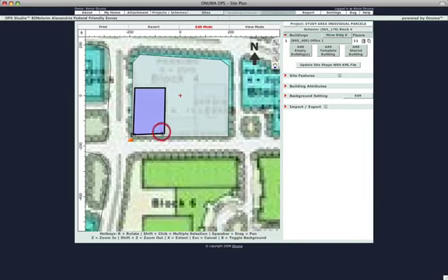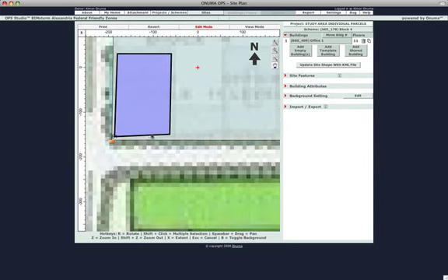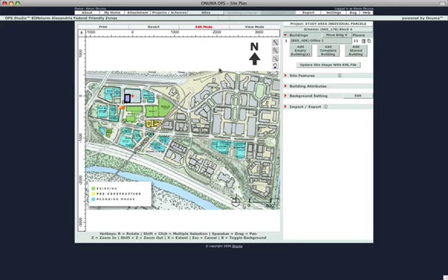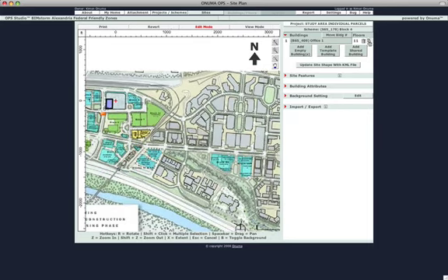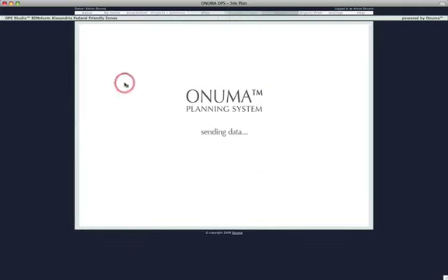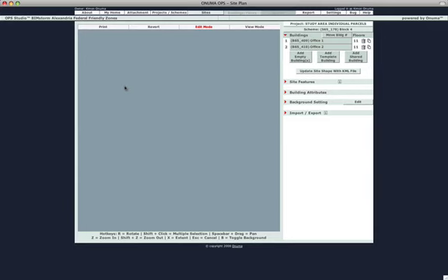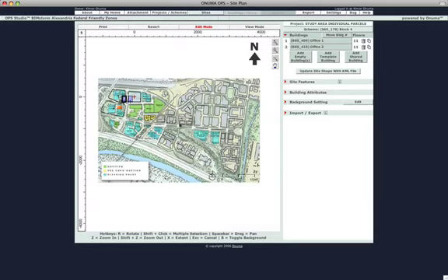We can correct the alignment of it, it is a little bit off maybe, but we can continue to work on that later as well. So one thing you can do right here is we have a building, we can actually duplicate it since it's 2 towers. Office 2. Proceed. And move that tower into position once it's duplicated. So there's Office 1 and Office 2.